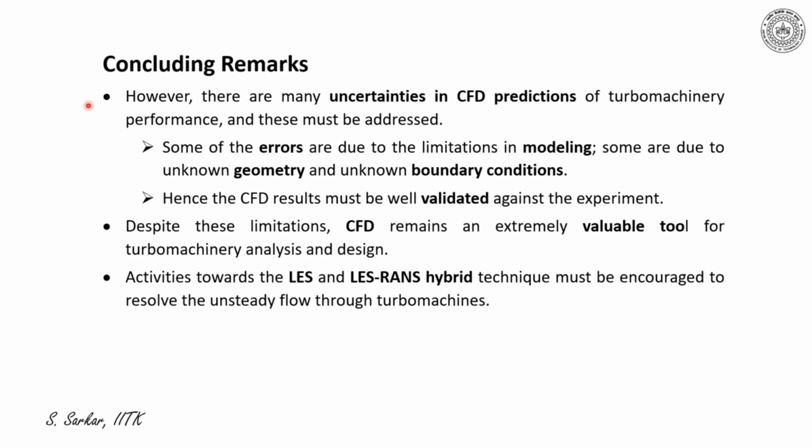However, there are many uncertainties in CFD predictions of turbomachinery performance, and this must be addressed. Some of the errors are due to the limitation in modeling, some are due to unknown geometry and unknown boundary conditions. Hence, the CFD result must be well validated against experiment. Despite these limitations, CFD remains an extremely valuable tool for turbomachinery analysis and design activities. Towards the LES and LES-RANS hybrid technique must be encouraged to resolve the unsteady flow through turbomachines.